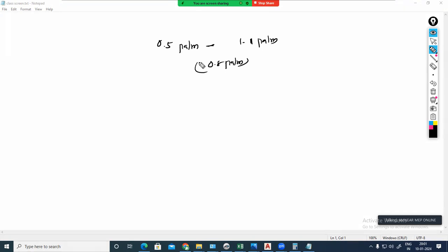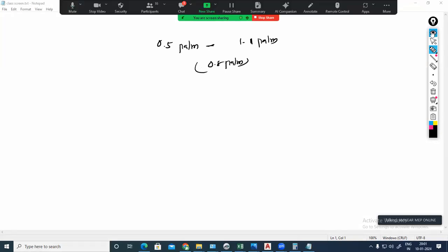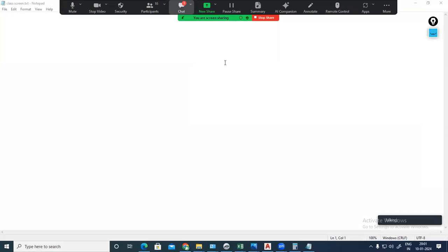We can change that. That is another story. But the problem is for higher flow rates. For example, if you are having a fan coil unit that is located within the space, in most of the cases the velocity will be limited to 6 meter per second. Correct, 6 meter per second.